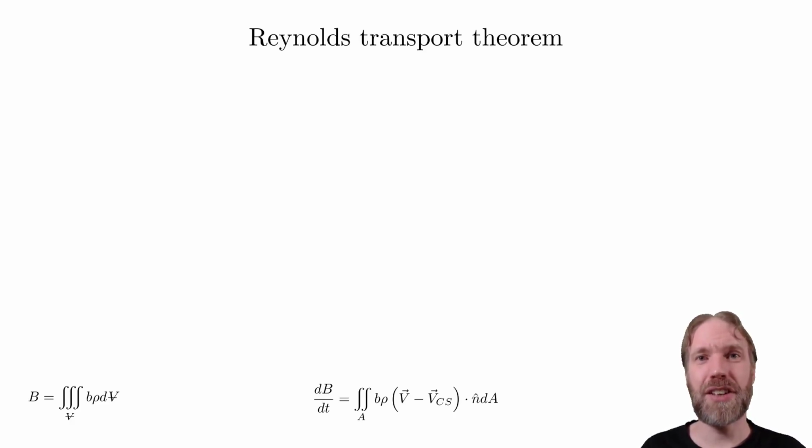To give a brief description, we want to study a given volume in space with fluid. However, the equations we are used to in classical mechanics are for a given object. This means that we need a way of converting our classical equations from a fixed mass into an equation for a volume that can have a flow of particles through its sides. This is what Reynolds transport theorem will do for us. We are going to derive it for any extensive property, and will therefore get several equations in one derivation.